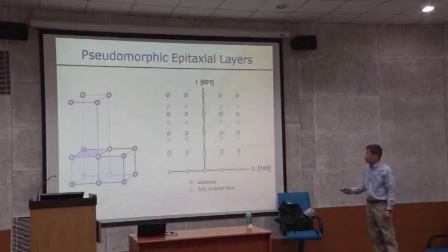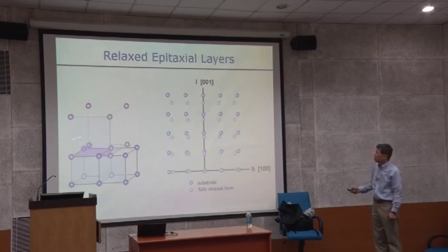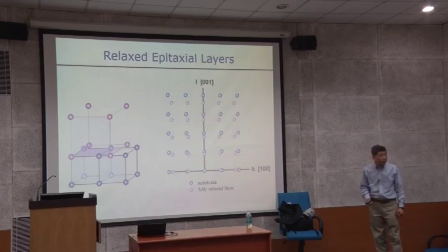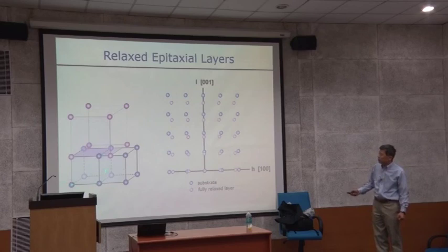And then I know the position is split. That means the lattice parameter of this and the lattice parameter of this one are not the same. But if it's incoherent, it grows like this. Look at this incoherent case, because barium titanate does not grow coherently. Which means it's not only vertically different, but in-plane is different too. So what that means is the 100 direction plane between this one and that one is the blue one here. This is the 100, and there's a 110 and a 001.